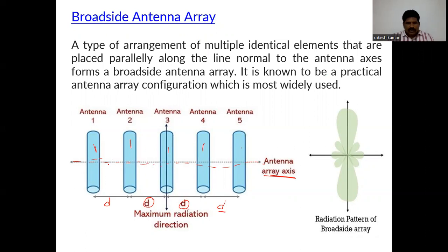If you make an arrangement like this and all the elements are fed with equal magnitudes of current and the same phase, then we will get the maximum radiation.